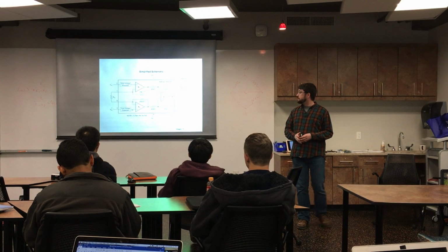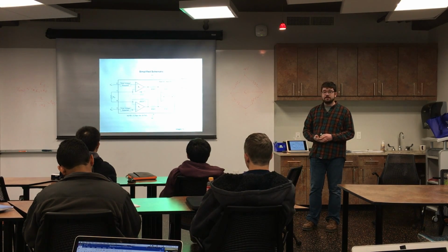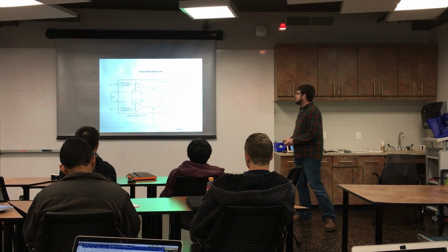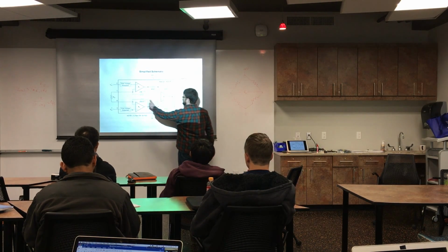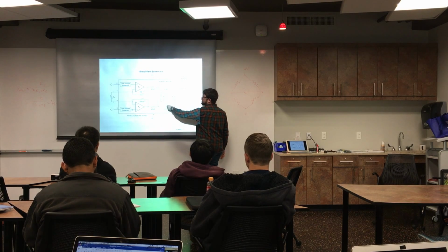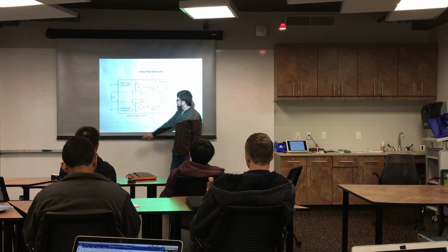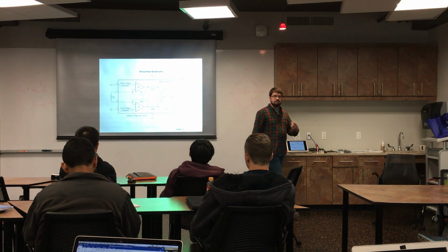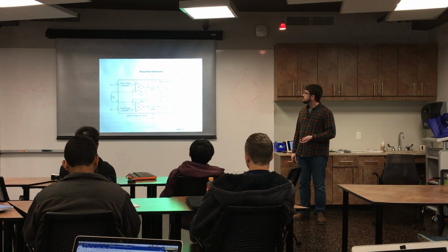And this is from the datasheet of the simplified schematic. So it looks pretty much like what we talked about already. There's a little bit of a feedback loop here. Then you've got the dividers going into the final difference amplifier. These overvoltage protection circuits up front are really just a couple of probably Schottky diodes in there.